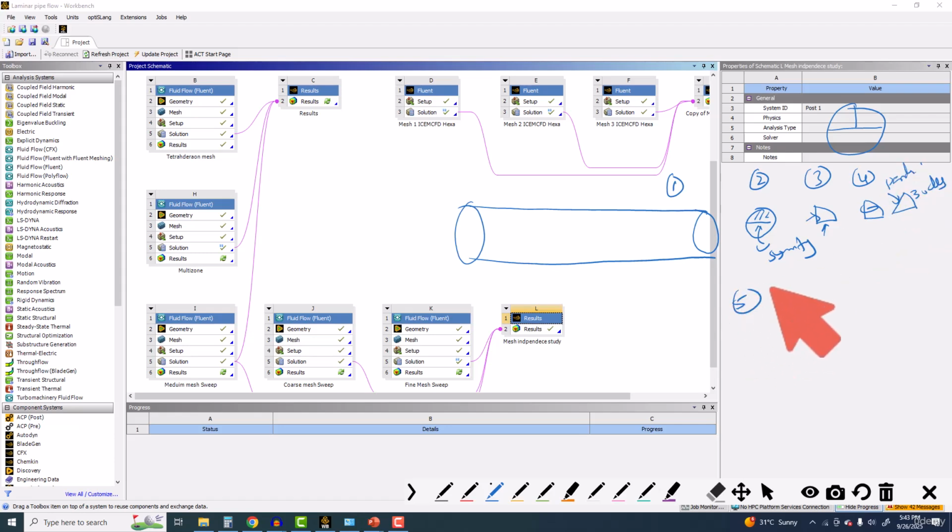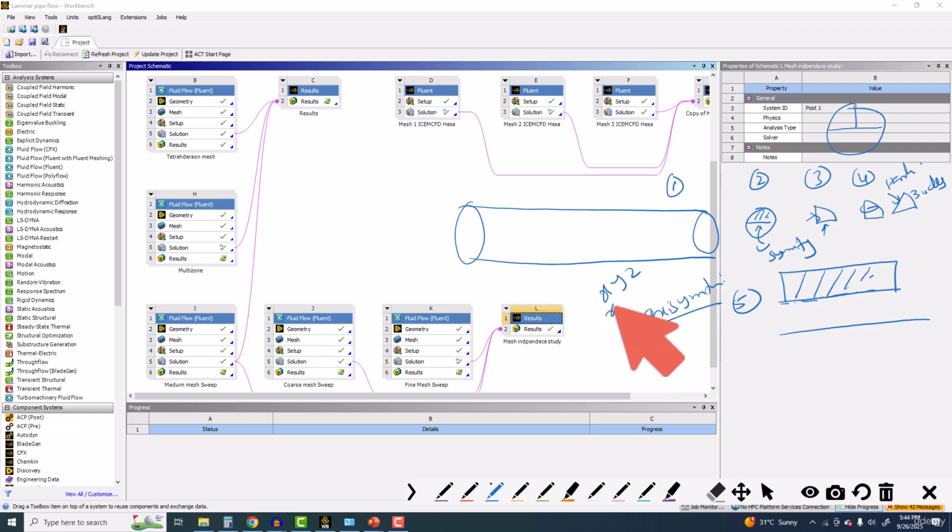The fifth case is going to be the axisymmetric case, meaning we will take only one plane. If the geometry is like this, this is my center line, so we'll take only this plane. In this axisymmetric case, we model only a single half plane. This shifts the problem from Cartesian x, y, z coordinates to cylindrical coordinates, so it will be r, theta and z. r is radial, theta is the theta direction, and z is the axial direction.